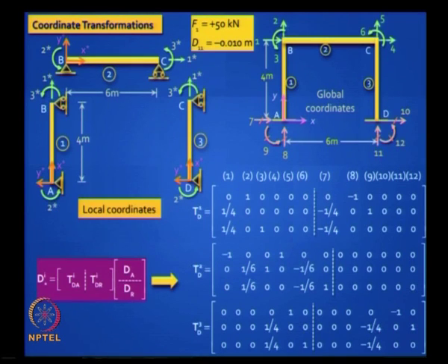So then your size becomes much easier, and it is full of zeros, so you just have to fill. In fact, when you program it, it's a null matrix, then you fill it only where you need to fill it. So it's very easy to actually program it. Okay, so you know how to get the TD matrix for a plane frame.